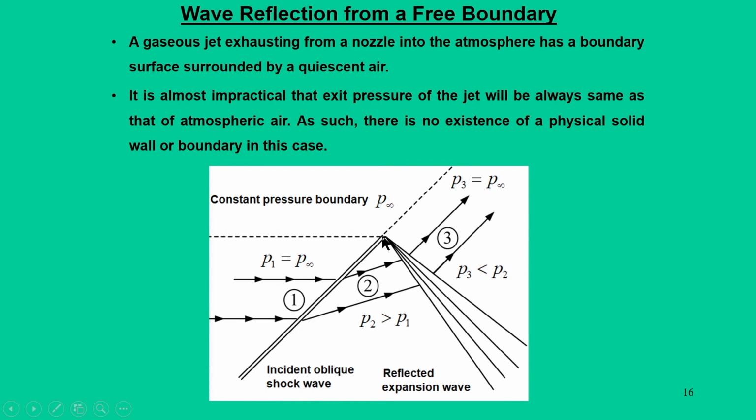Now, when the static pressure rises, and the incident shock reflects, you can see this constant pressure boundary gets deflected upward. When it gets deflected upward, you can imagine that for this oblique shock it acts as an expansion corner. That means for the streamline it acts as an imaginary convex corner, so it must come out as expansion waves.